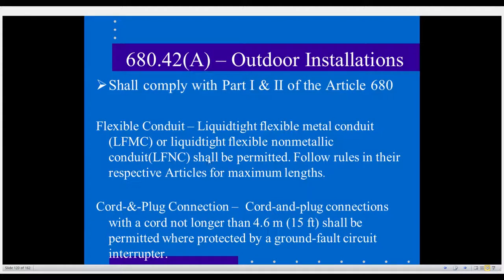So when I say that, it's permitted to use them on these outdoor spas and hot tubs in lieu of the requirements that would be in Part 2. However, you got to make sure that you do follow the rules for each one of these articles that are associated here. You have to make sure that you follow those. Now, another method would be cord and plug connection. So a lot of these units already come with a cord and plug connection, all right? And most notably, the 30 amp ones that are 15 and 125 volt type of plug with a maximum of 30 amp connection on them.